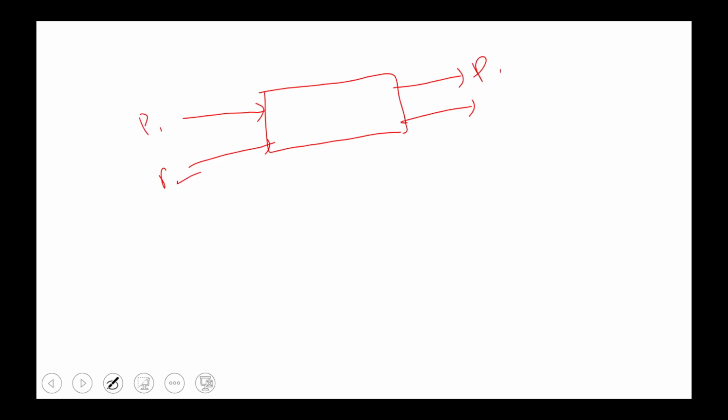So, you have given a 2 by 2 coupler. This is your coupler. Your one power is splitting like 60:40. So I suppose the 60 is this and the 40 is this. And there is an insertion loss of 2.7 dB in this case, and in this case the insertion loss is around 4.7 dB.